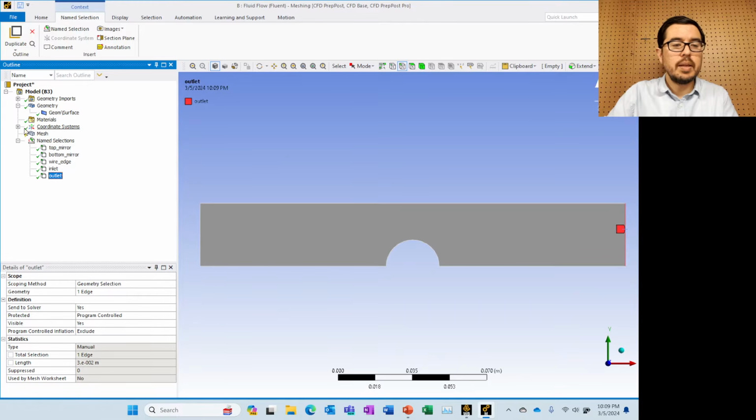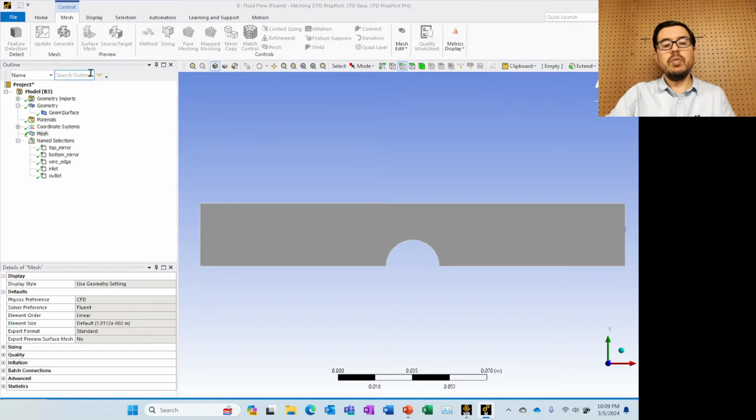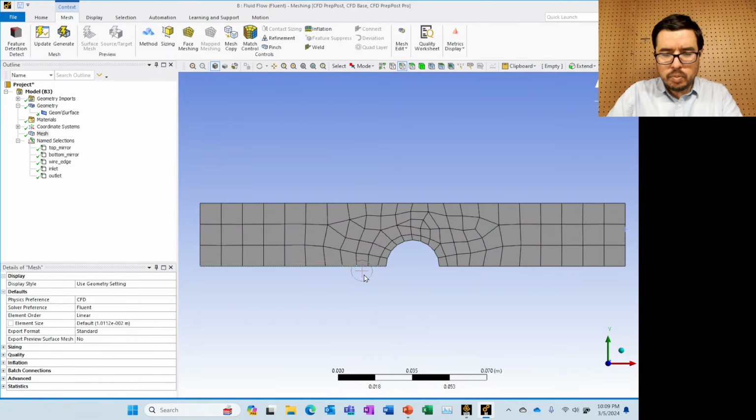Wonderful. Now let's go to mesh. If we generate the default mesh, we see that, well, it does have a mesh, but not exactly capturing or has the ability to capture what we think some of the interesting physical behavior might be. We understand that a lot of what happens in a simulation with finite volume is based on the number of nodes, right?